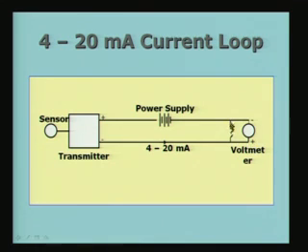For example, I may want 5 volts or 10 volts across this, and this resistor has some particular value chosen such that it gives you 5 volts. So this 5 volts plus whatever voltage drop takes place in all these other wires and so on, that the power supply must be able to supply. That is the important thing. So the strength of the power supply is determined by the potential difference required here at the user end, and also the losses in the wires, because the current is going to pass through all the wires, and the sensor itself may require power, which is also drawn from this power supply.